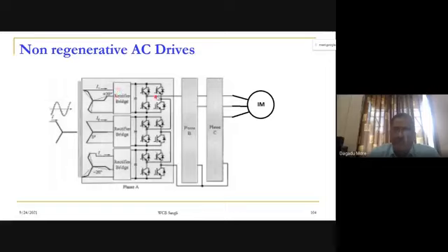For one phase, each H bridge requires a separate supply, which is obtained with the help of one rectifier bridge. For one leg we require 3 rectifiers, another leg also requires 3, and the third leg also requires 3. So the total number of 6 pulse rectifiers will be how much? 9. We require 9 rectifier bridges, 9 H bridges.